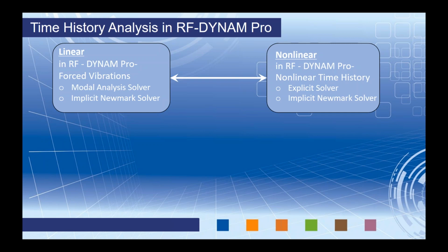Now, again, nonlinearities in the model are replaced, as I've already mentioned, with tension-only members, but also with compression-only members and cables. They're all replaced by truss members. And by the way, a truss member in RFEM is nothing more than a typical beam element that can take both tension and compression, and all we've done is release the moments. Now, other nonlinearities may be completely ignored, such as support conditions.